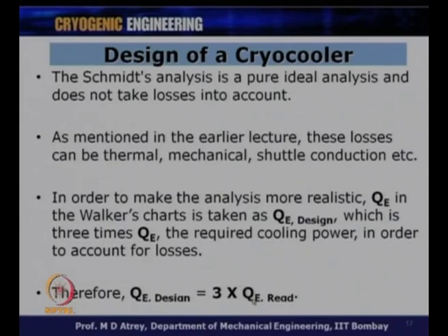If I want to design a cryocooler for 100 watts, I will now design it for 300 watts, assuming that out of this 300 watts, 200 watts are losses and only 100 watts are going to be delivered to the user. Therefore, I will take QE design as what I earlier took as QE when I refer to Walker's charts. This is an important consideration, the design QE value.